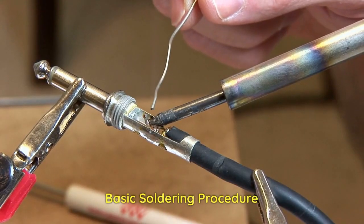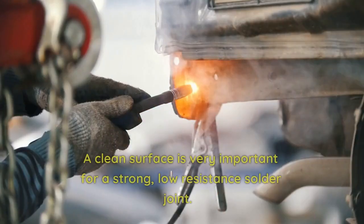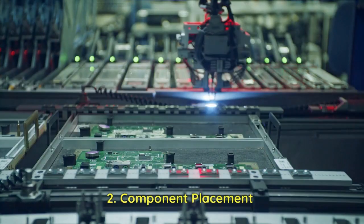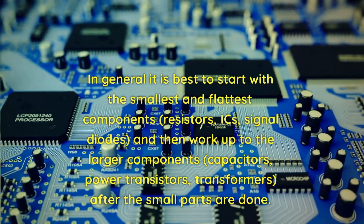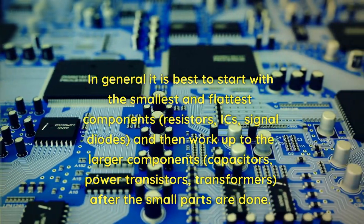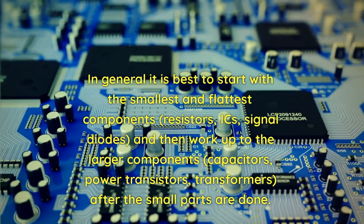Basic soldering procedure. 1. Clean the surface of the PCB. A clean surface is very important for a strong, low-resistance solder joint. 2. Component placement. In general, it is best to start with the smallest and flattest components: resistors, ICs, signal diodes, and then work up to the larger components: capacitors, power transistors, transformers, after the small parts are done.